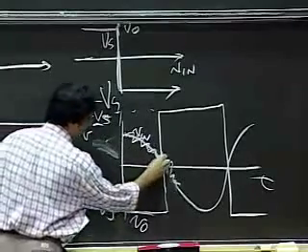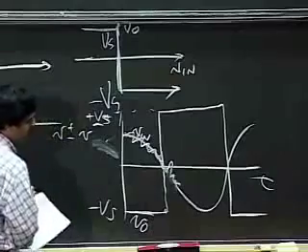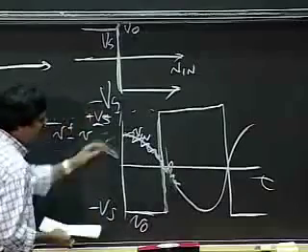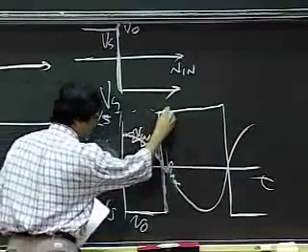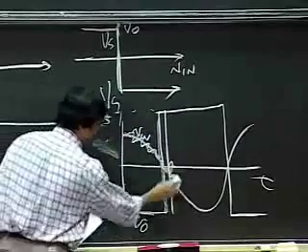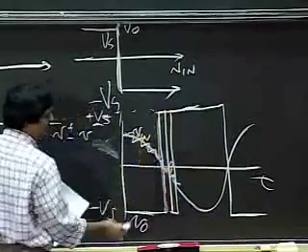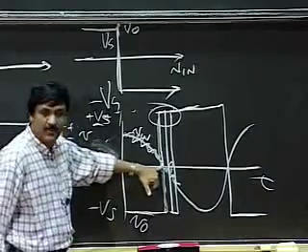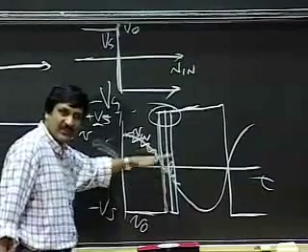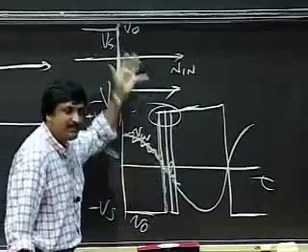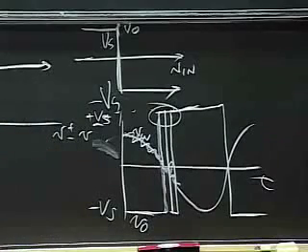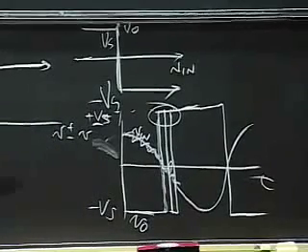So what happens is that at this point, where the value goes negative, I do bump up. But when, for a second, I have my input going above 0 again, this output comes down again, and out here it goes up again. So I get this nasty behavior at the point where the input is around 0. Okay, so when the input is meandering around 0 because of noise, I get a huge amount of up and down glitches on the output. Okay, that's not very nice. And we'll do a little circuit that attempts to fix that little problem.